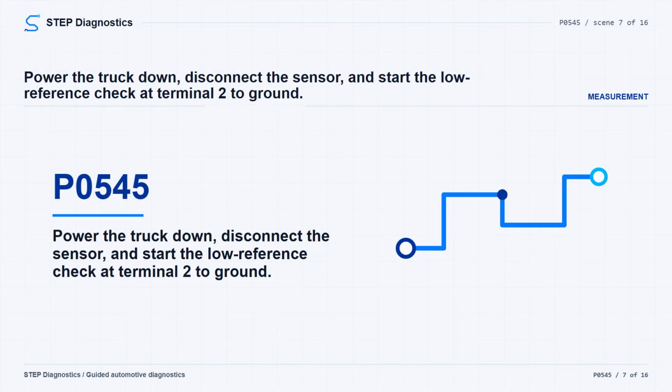For circuit testing, turn the ignition and all vehicle systems off. Give the modules time to go to sleep. It may take up to 2 minutes before a ground or low reference continuity test is accurate. Disconnect the appropriate B131 exhaust temperature sensor connector. Test between low reference circuit terminal 2 and ground. You want less than 10 ohms.